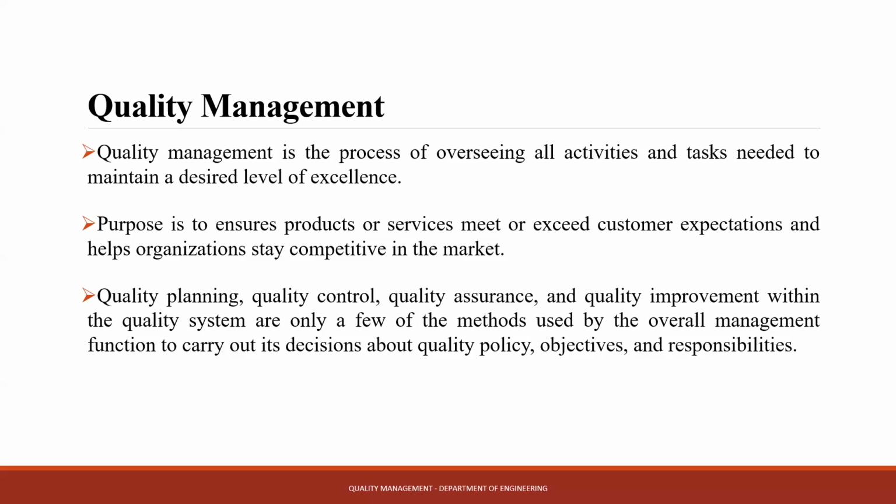You know, when it comes to quality control, we use some statistical techniques as well to analyze the quality. Right? In this quality controlling, we have some quality related limits: upper control limits, lower control limits. Likewise, we have quality related specific limits. So while conducting the measurement and the monitoring, we can check whether we are within the specified limits or not.